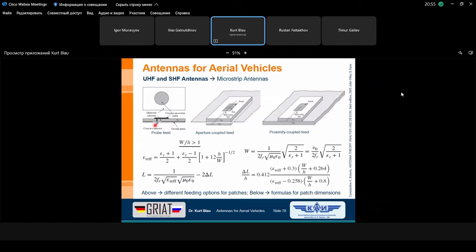Here we have a coaxial feed, which goes through the ground plane over an iris. It's, let's say, an etched hole, and then with the inner conductor, because the substrate is not very thick, it's only 1-2 millimeters, or sometimes smaller, depending on the frequency and the permittivity of the material. Then it goes through. Normally here is a solder point, but it can be connected with other techniques, or without galvanic contact.